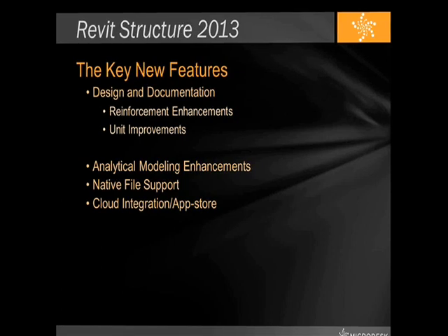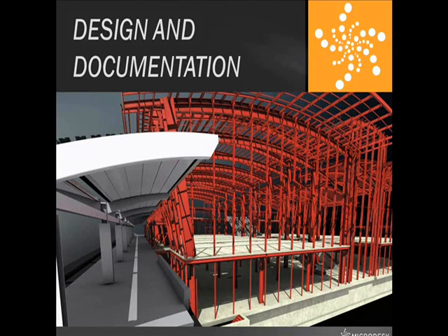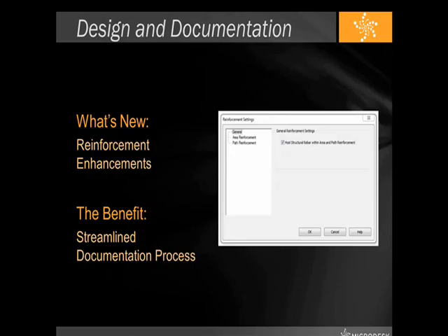I will now go over some of the rebar enhancements that will be beneficial for design and documentation. For 2013, area and path reinforcement has been updated with a new behavior that makes these elements function in a similar manner as beam systems and structural framing. The creation of these elements stays unchanged.